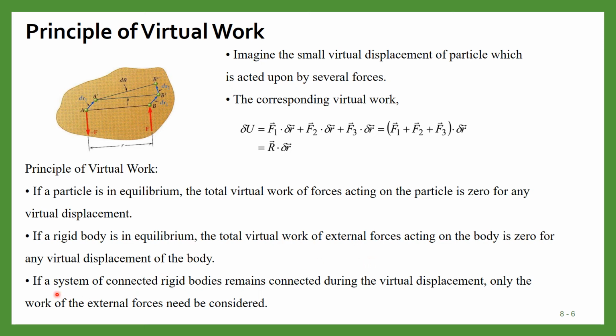The third point is, if a system of connected rigid bodies remains connected during the virtual displacement, only the work of the external forces needs to be considered. So if there are several rigid bodies which are connected, we will consider the displacement only because of the external forces.